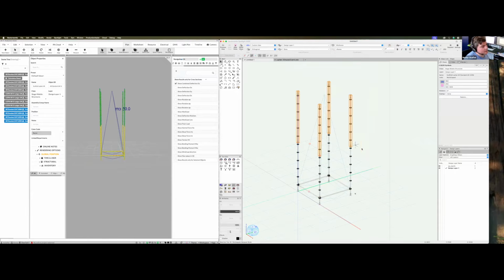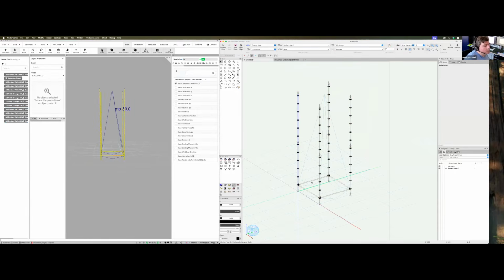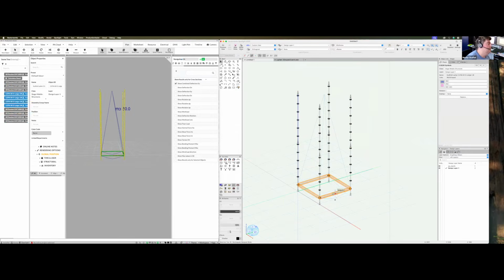So I have set it up like this, and we want to make a scaffolding thing. So normally you put in the ledgers in here with some kind of raster. So a good practice normally, just because of the diagonal force, is to go first 1 meter, then 2 meter, or 1 meter, 1 meter, 2 meter in here. We want to put a little stress on this thing, so we immediately will go only the 2 meters up.